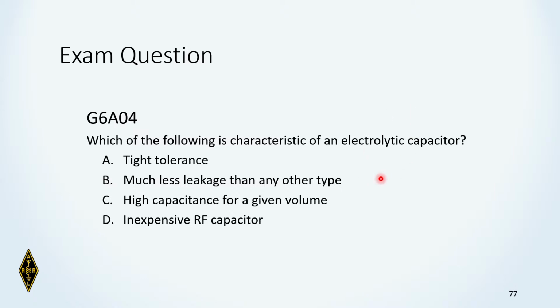Electrolytic capacitors do tend to dry out. The insulating material a lot of times is coated, and one that's aged has probably lost much of its capacitance. One of the things that hams do when they're restoring older equipment is typically to automatically replace all of the electrolytic capacitors. They do age and dry out.